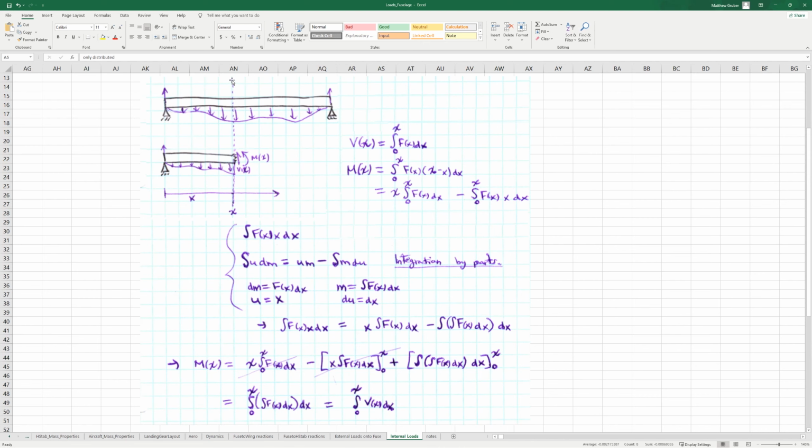So if we do a free body where we slice it here, then physically you can clearly see that the shear is a function of just the integral. The shear at this chi is the integral of the forces, including this point force and all this distributed force. It's the sum of it, the integral of it along this whole length, so that this situation balances.